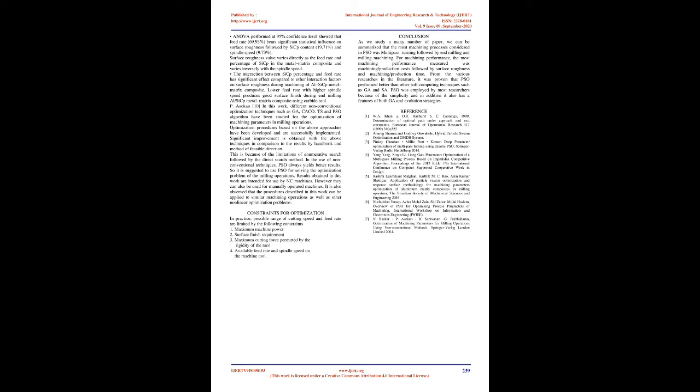Surface roughness value varies directly with the feed rate and percentage of SiCp in the metal matrix composite, and varies inversely with the spindle speed. The interaction between SiCp percentage and feed rate has a significant effect compared to other interaction factors on surface roughness during machining of Al/SiCp metal matrix composite. Lower feed rate with higher spindle speed produces good surface finish during end milling of Al/SiCp metal matrix composite